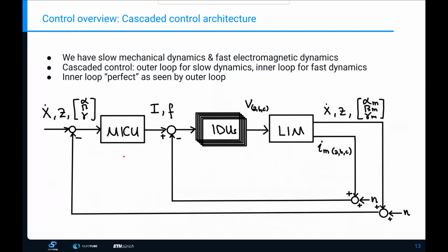The actual linkages of the electrical system are honestly not yet integrated into the models, but as it looks, I cannot really tell you how fast we have to go. I can maybe tell you that the outer loop is probably going to be run at 200 hertz to 1 kilohertz, while the inner loop will be run at whatever the maximum current sensing capabilities we will have.